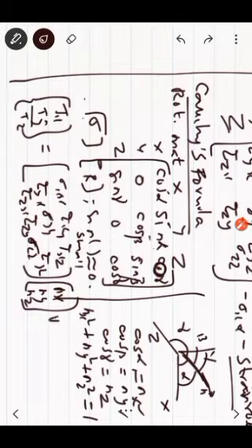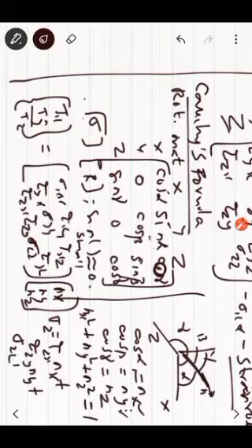You can write tz, resultant along z direction, is equal to tau zx nx plus tau zy ny plus sigma zz nz. So like this you can write for tx, ty. So I am writing that. So this is tz. This is the Cauchy formula for z direction.